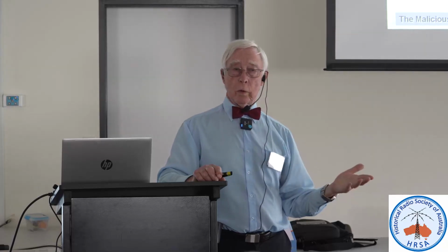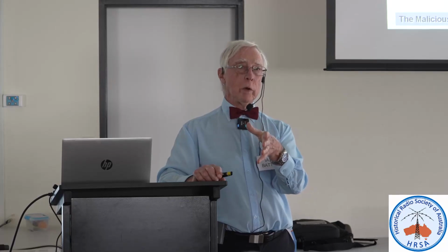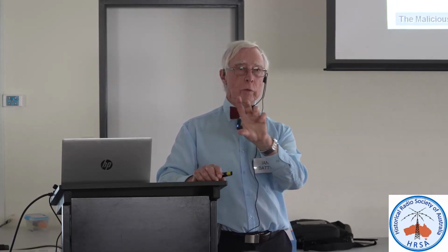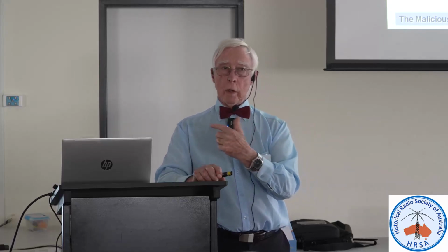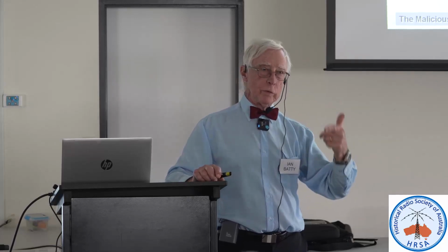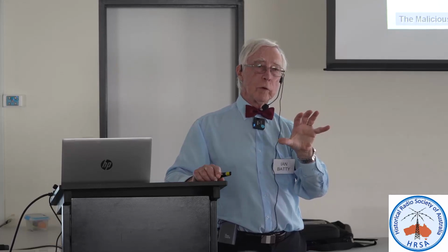But that's my particular approach to it. And what you're doing, you're actually certifying every component, and you can be quite certain that as you go through and do your measurements, you're discovering faulty components, which with my method, I would have to go through, find a DC voltage was wrong, and then deduce the fact that some of the resistances in the circuit were crook. So it was horses for courses.